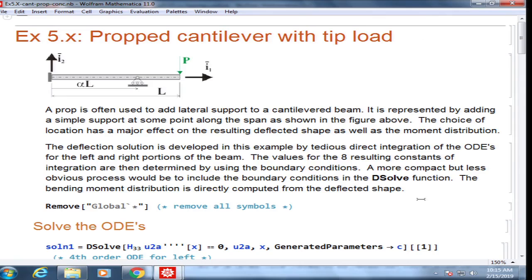For example, if I have a beam like this, and if I fix the displacement here and here, then if the beam bends, it would have additional axial stresses in the middle or anywhere in the interior of the beam. The reason for that is that you are not allowing the actual displacement to compensate for the length. That's why the displacement is allowed in the longitudinal direction, but it has no implications whatsoever for bending. The only thing it does is prevent the vertical displacement u2 at that point alpha L, right? So let's see what we can do for this problem.